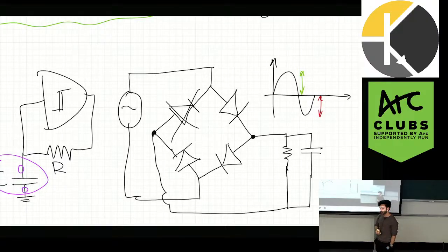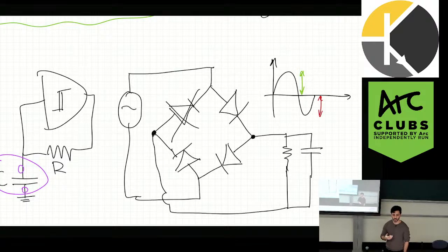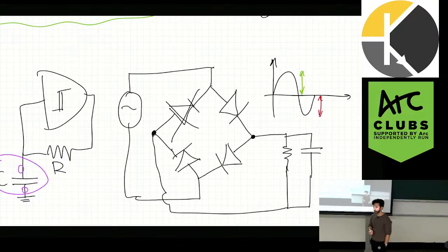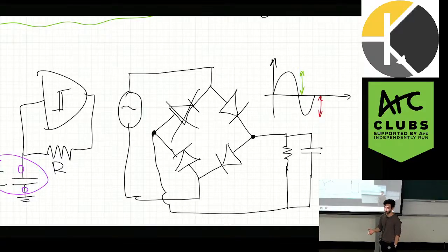That sort of makes sense. I think this one does require practice. A good exercise for this one is to go to circuits that you've already learned and just ask yourself what happens for different components. That's likely what a question is going to be. So you can't say half negative. Yeah, so exactly, half-wave rectifier. Exactly. So we say it still works, but as a half-wave rectifier now. But the positive doesn't change. Yeah, exactly. Does that make sense?